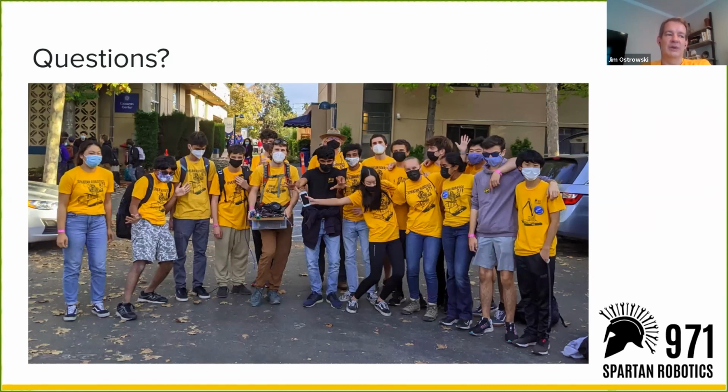I think we could probably do 5 cameras at basically 1 hertz, if we want to do it all in one Pi. And the catch is that the Pis right now use a MIPI interface to get the image from the camera onto the Raspberry Pi, and I believe there's only 1 set of lines for that. So you'd be limited on how you brought the information from the camera to the Pi, although potentially you could do USB cameras or something else like that. But currently it is 1 Pi per camera.